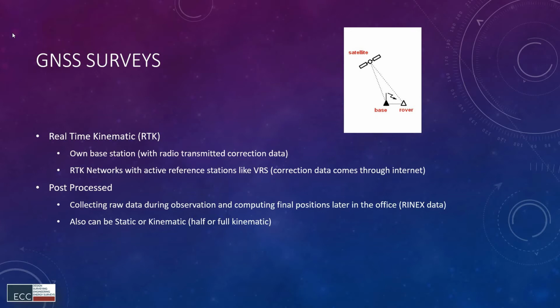The next step is that we can bring in all the rest of the survey data in relation to our base, which will be fixed. At the same time, the other control points observed with the rover will be fixed from our base point with a vector.